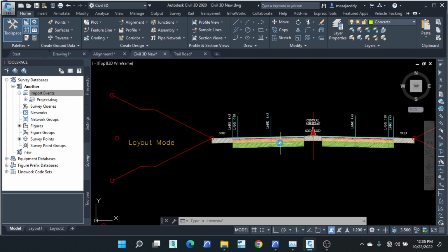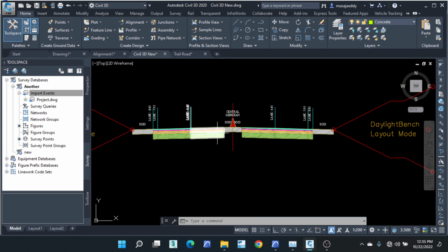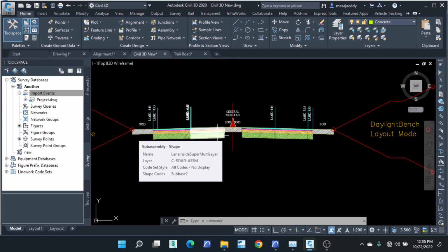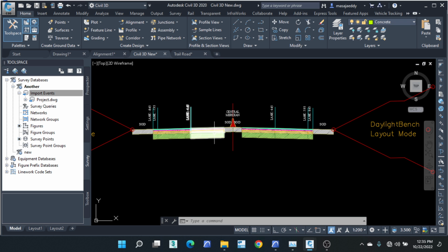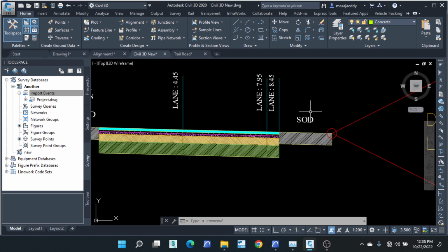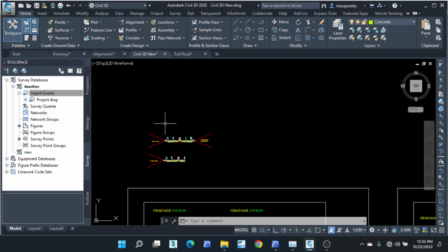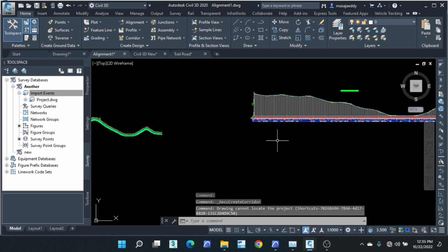It's okay, you can go deeper. Fine. So this is what an assembly is. It's just like the different road layers that we're going to be using to create our road. So you have a lane, then a side drain, then a daylight. You get it? We can only create a corridor if you have an assembly, an alignment, and a profile. That's what we are lacking here.